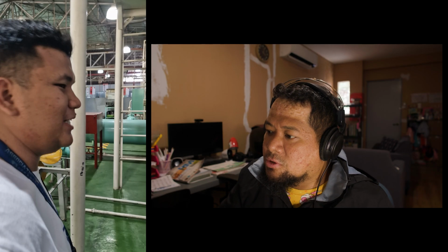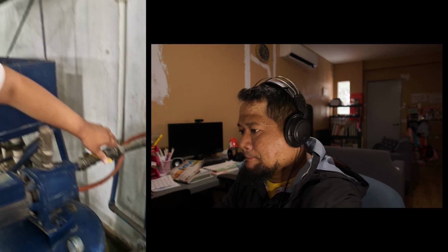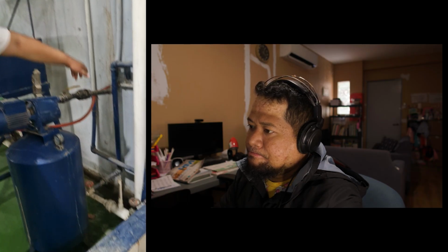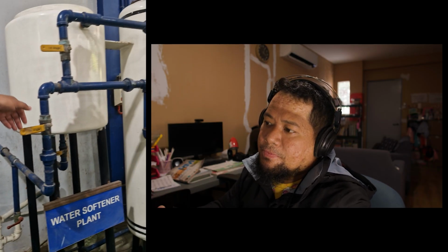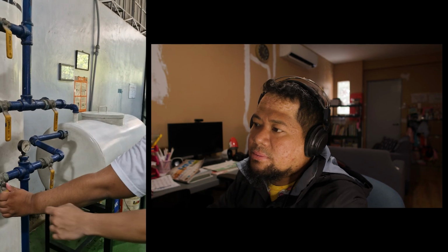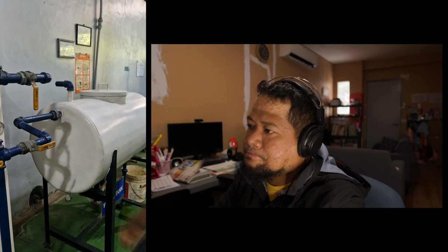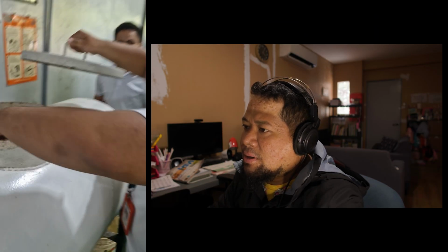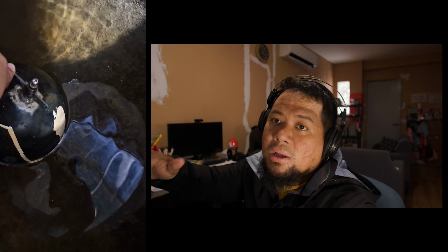So here's one of my students, Ralph. He's going to start the boiler, and he'll be showing to us the steps. So open this valve. We are lining up for the water tank, and then from the water tank we are going to feed it to the boiler drum, where water is stored inside the boiler. The tank is full, and then we have a floater just in case it will be full, it will automatically stop.